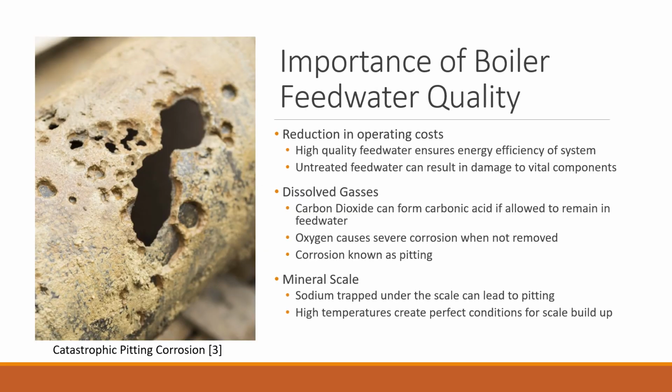Now that we've discussed the history of boiler systems, I think it's important to understand the boiler feedwater quality. When using a low-quality boiler feedwater, you're going to experience a significant increase in operating costs. This is because low-quality feedwater lowers the energy efficiency of the system, making it work harder for your desired output of steam. Additionally, untreated feedwater can result in damage to vital components like your piping, your pumps, and even the boiler itself.